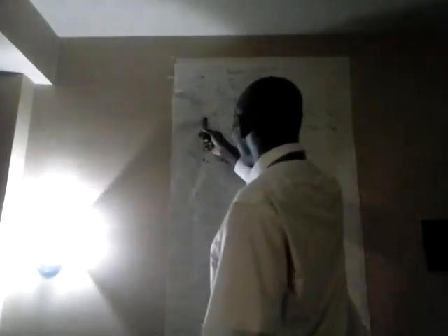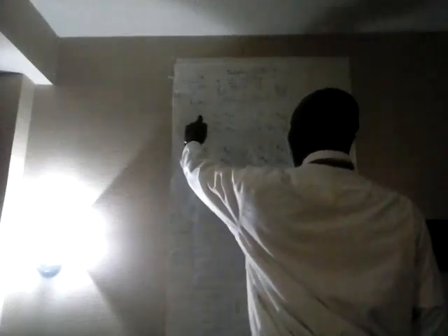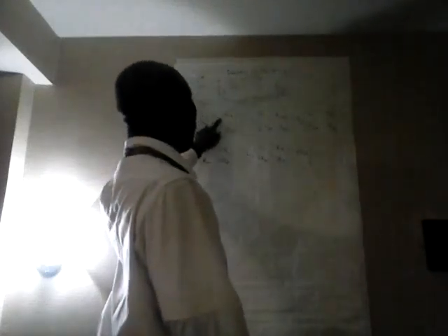So that will be R22. Remember, I'm saying these things: the mutual resistances are negative, as well as this is a sign. And there's a way to calculate the signs of these elements of the matrix. But for now, we'll just say that if this is the first row and first column, then 1 and 1 is 2, it's even, then all even elements take on a positive, and all the negative are the uneven numbers. So we add 1 and 2 here.